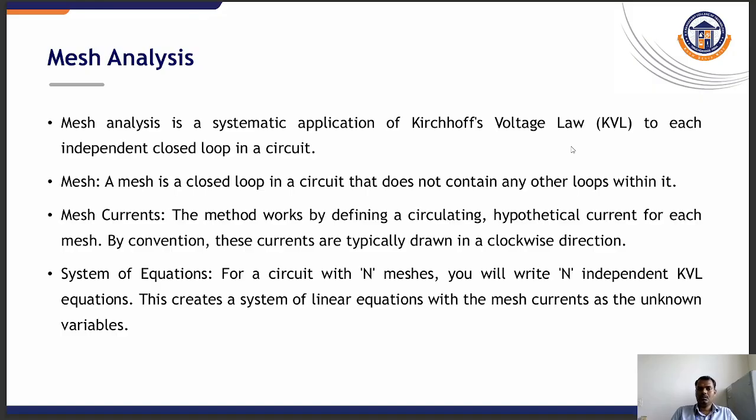Next we shall see about the mesh analysis. Mesh analysis is a systematic application of Kirchhoff's voltage law to each independent closed loop in a circuit. A mesh is actually a closed loop in a circuit in which we don't have any other loops inside it. So a mesh is a separate closed loop. And then mesh current means the method works by defining a circulating and hypothetical current for each mesh.